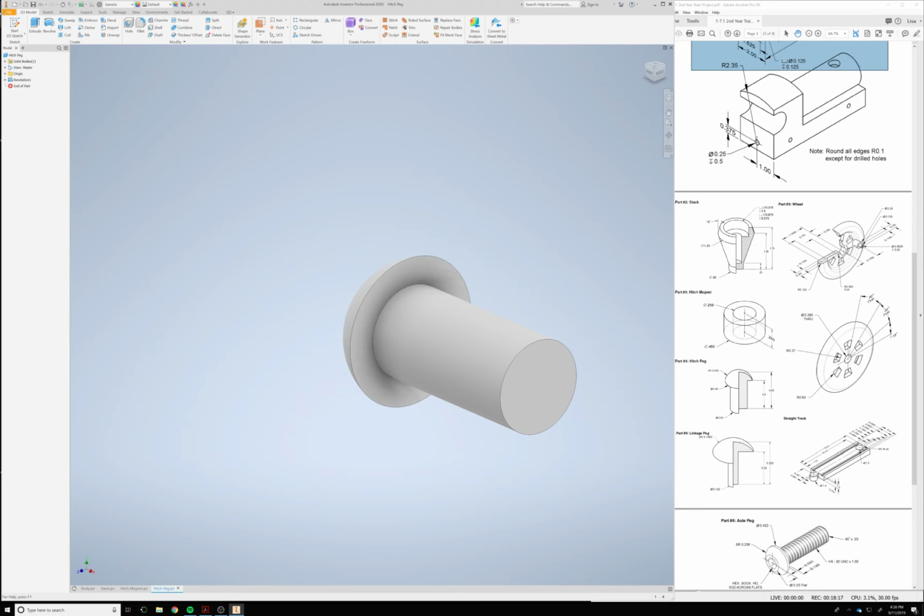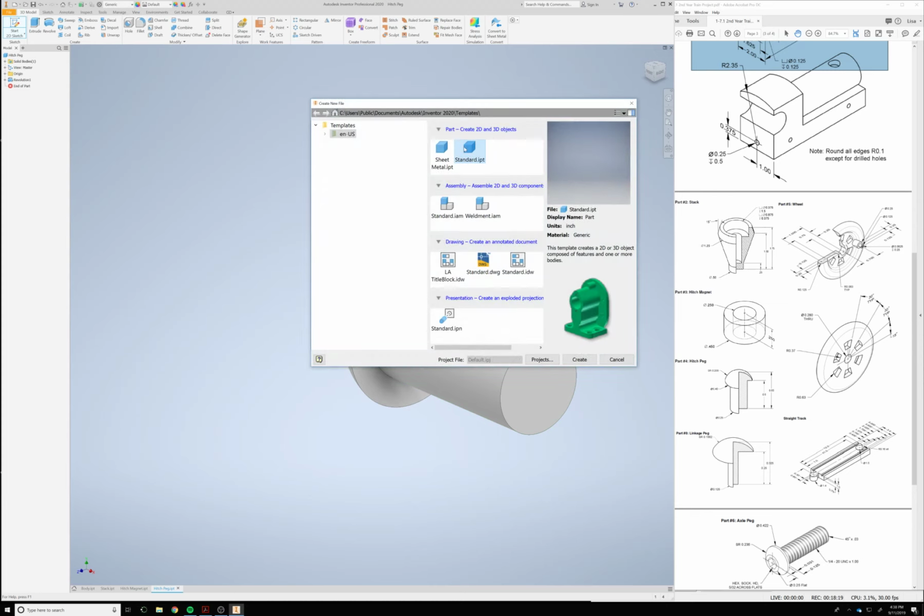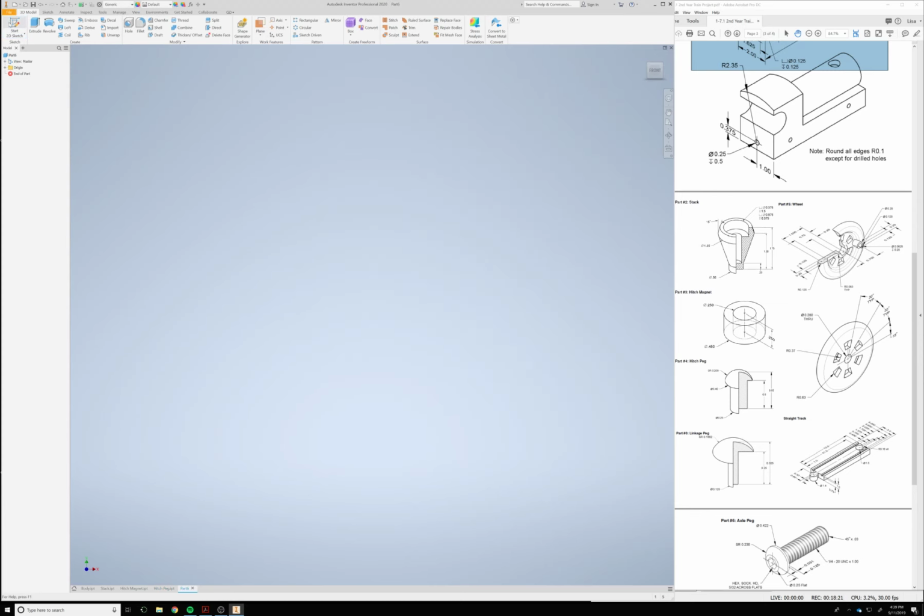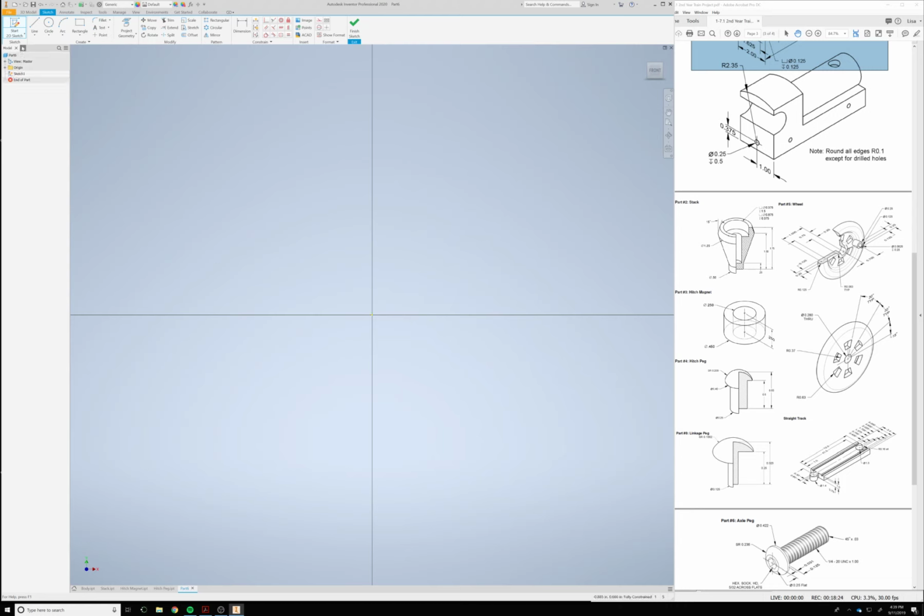Let's go ahead and do the linkage peg. I could say for you guys to do it on your own, but I'm on a roll. I'm feeling generous today. So let's go ahead and create, very similar to what we just did. I'm going to just go straight down from somewhere above the origin, and I'm just going to draw this general profile and then put an arc in. Okay, going to use my tangent constraint so that way I know that it's tangent here.